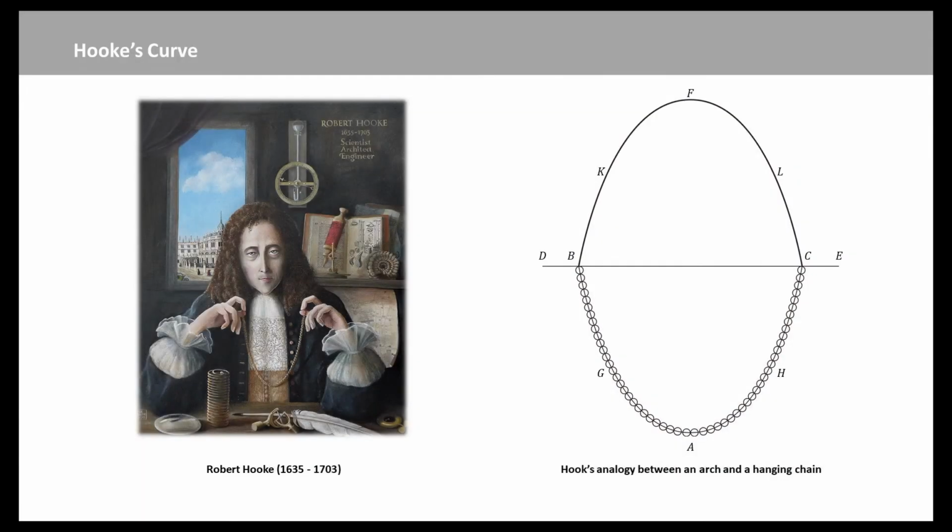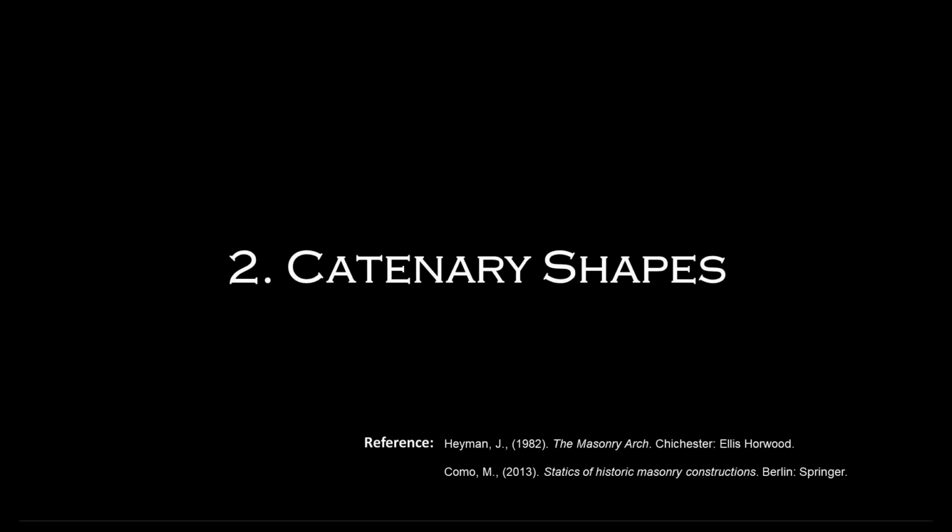The research conducted by Robert Hooke at Cambridge led to the formulation of the resistant model of the arch, using the funicular curve of the loads. The arch, whose axis is upside down with respect to the hanging chain, the catenary, can sustain the same loads, determining the equilibrium curve of the chain. In 1675, Hooke realized the importance of studying upside down or inverted systems to analyze the equilibrium of masonry arches. It is worthwhile deriving the equation of the catenary.